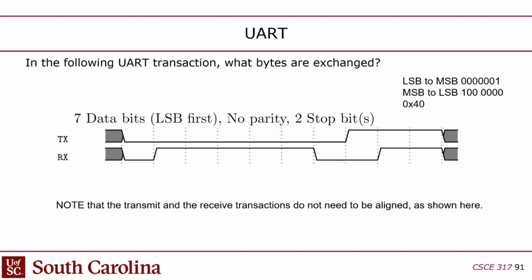Because there's no clock, these guys have to have an internal clock, which is fine. I mean, the internal clock will give the same clock speed, right? Which means the bit periods are the same on the sender and the receiver, right? But the phases are not locked in. That's the problem, the clock phase. There's nothing to make the clock phases consistent. So even though the clock periods are the same, because the phases are different, you could end up reading this guy when he's in a state of flux, right?